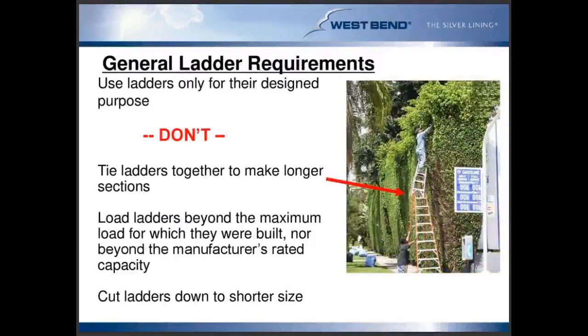Other general requirements: again, making sure that we use it for its design purpose. In the event that you need to get a little bit further up in the air or a little bit higher elevation, we cannot tie ladders together to make them longer, like you see in the picture to the right. And again, as I've mentioned a few times now, we can't load them beyond their maximum load capacity.